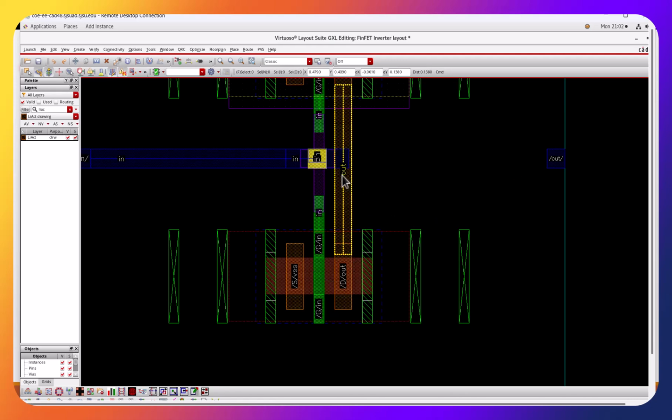Maybe this is not a good way because this might have a bad, no, I mean, this is a good way for, this is local interconnect, right? But maybe it has a larger resistivity or whatever, or capacitance has a problem. But the reason I do that is because I cannot put metal one here, or maybe I can put it here, but still I need to go through, right? So let me just leave with this.